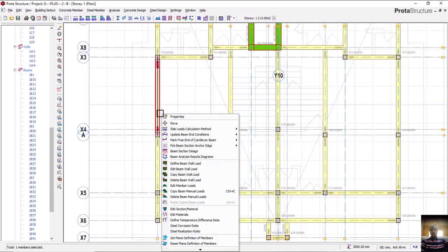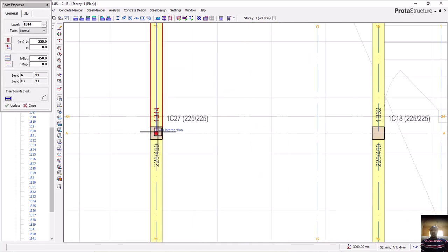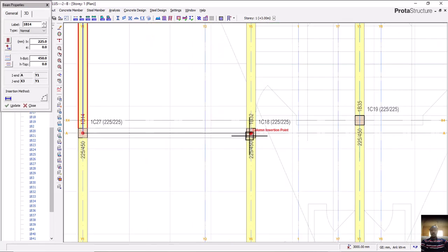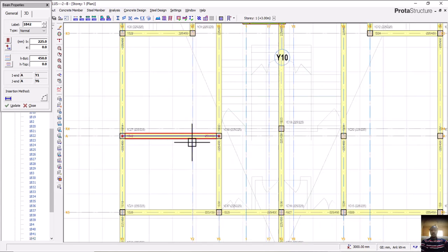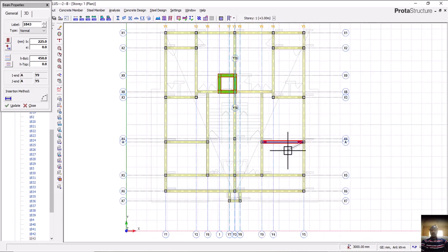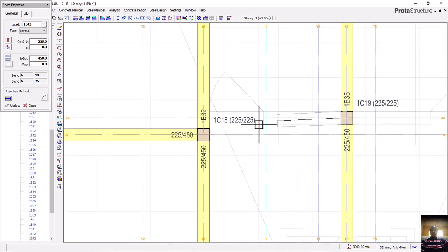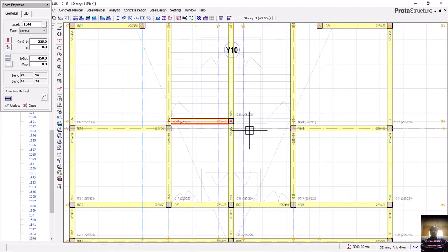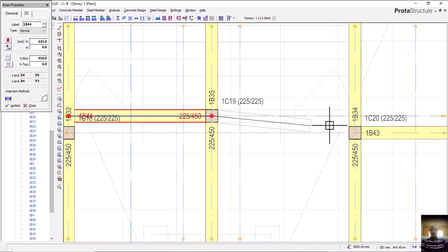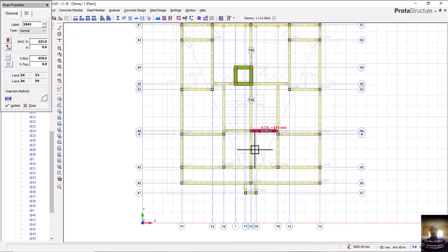Understand? So let me just break it into 2. Since my maximum we are talking about, try to consider, is a 30 square meter, and I don't want to use a bigger slab thickness. So that 30 square meter is still okay. So this one now come here like this. My staircase is around here. Is that okay? And this one also is around here. Okay. Alright, this is my staircase now.